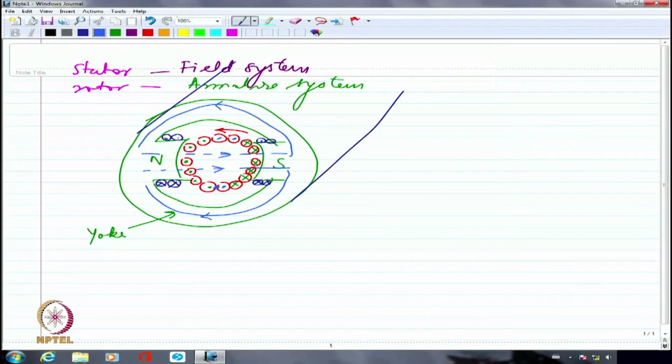Some of you pointed out in the last class when we were drawing the winding diagram that if we had taken, say, north pole here and south pole here, the conductors that were somewhere in the cusp of south pole or north pole, one of them was dot, one of them was cross. One will carry current in upward direction, the other one in the downward direction, and they are right adjacent to each other.